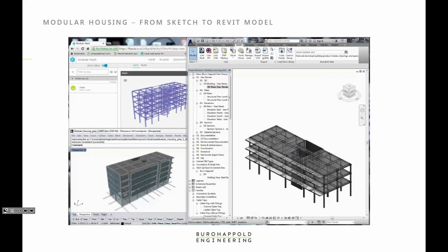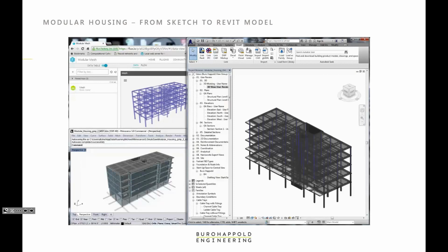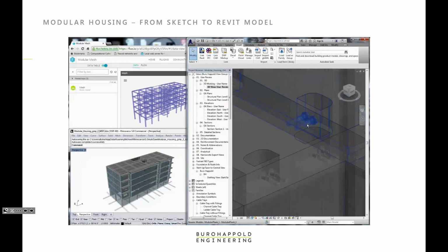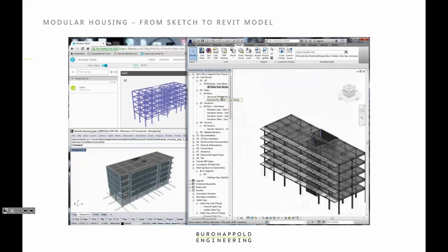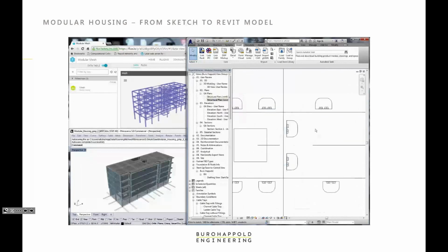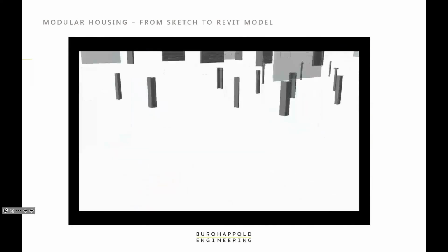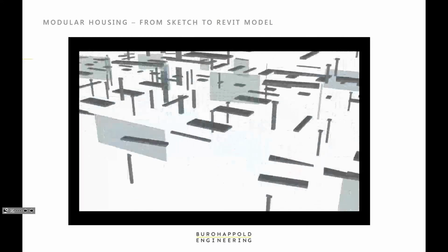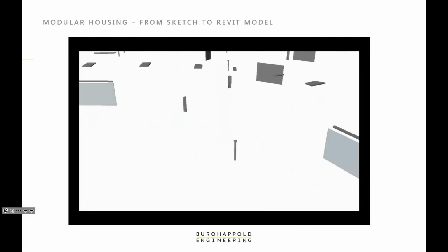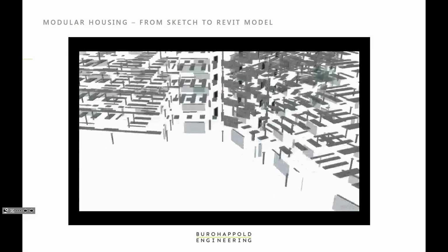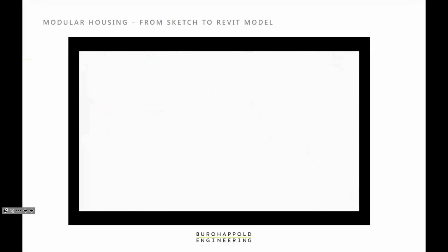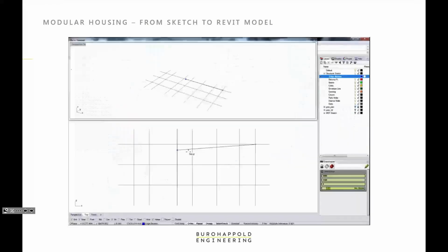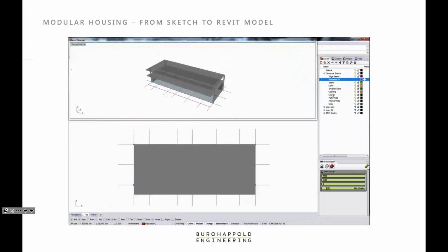They're pre-sized based on a maximum span, etc. By sketching in Rhino, the script takes care of the rest of the development of the building information model, and it means that you can apply the same modular parts of the structure to different building typologies. As long as the columns are always at a maximum spacing and the cores are a certain height and aspect ratio, then we know that the structure works because it's been pre-calculated.